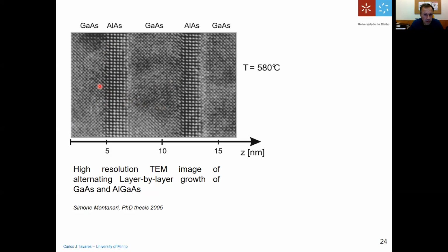Okay, but anyway, take into account that the first layer is less than 4 nanometers, and the second one is about 3-4 nanometers. Okay, we can see that in fact we are producing a bilayered material which grows epitaxially. And of course, this can only be achieved if you are making the deposition at a very high temperature, around 580 degrees. And here, by using such high temperature, you can give the necessary energy for the atoms to move around and look for preferential sites to start growing in